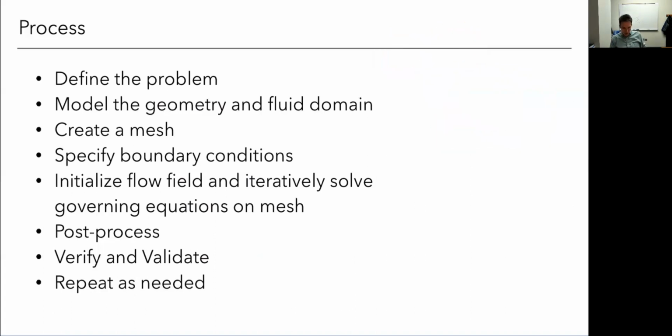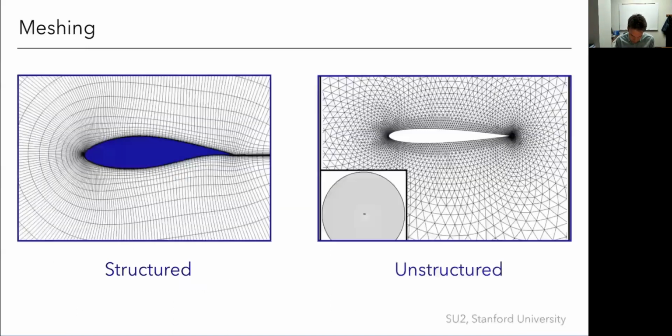Okay, so after I've figured that out, I then create a mesh. This is, I would say, of all the steps, probably the most challenging from a CFD expertise point of view, because everything drives everything, but the mesh is really critical to get right. And it's hard to know, did I put enough cells in this spot? Because if you didn't, it's not going to be accurate enough. So for the mesh, I have some pictures here. Here are some pictures of some meshes. These are some different types of mesh. But how do I know, right? Did I get enough resolution here?